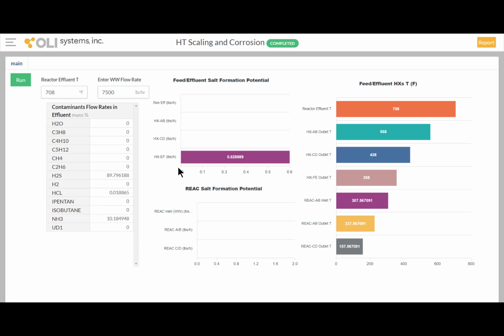So you can make those changes on the fly and redeploy into the field so that operations and process teams can monitor these exchangers, answer those questions on a shift-by-shift basis or a couple hours basis, and continuously track the reliability of the unit so that you can extend the unit life through the turnaround. So turnarounds used to be 4 to 5 years. Refineries now are trying to push 6, 7 years. And this tool gives you the ability to get to that point, because not only do you get to monitor for reliability, you get to exactly understand where the fouling happens in the feed effluent exchangers.